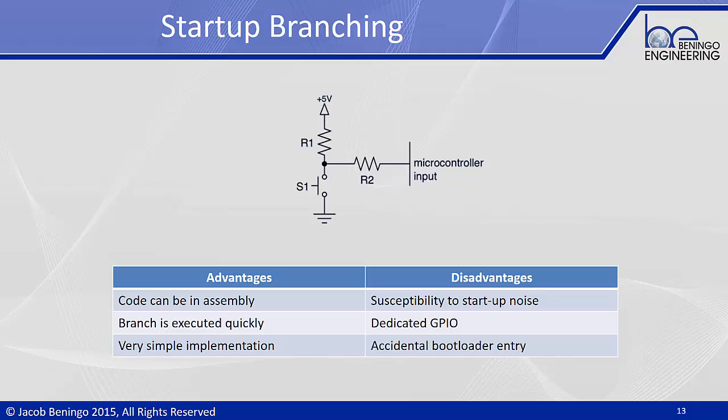And then third, and probably the biggest factor, is that we could accidentally push this push button and load the bootloader by accident. There's nothing like getting a call from your client or end user saying that they've broken their system, they don't know what's wrong with it, and all they've done is accidentally pushed some hidden button in the system that forces it to load the bootloader rather than the normal application code.